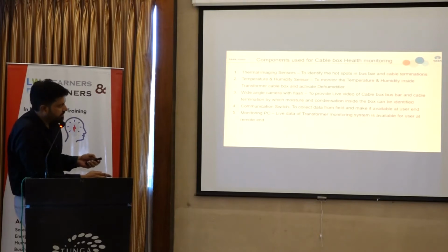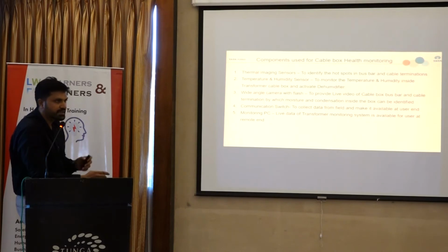There are wide angle cameras with flash inside the cable box by which we can do real time monitoring of the cable box, any condensation or any moisture, those things. And we use a communication switch and also a monitoring PC to monitor the transformer cable box health from the remote end.